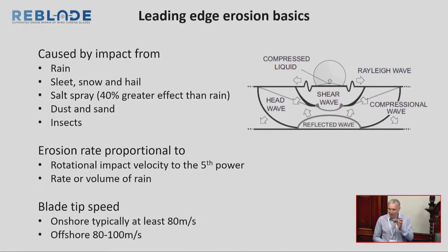Okay, so it makes a massive difference as that tip speed comes up, and people are only just starting to realize that, which is why a lot of offshore turbines that were designed for 25-year life are finding that their leading edge erosion problems are starting after about 2 years. This is a big, big, big issue. Also offshore, you tend to get more rain. So that relationship is about 2/3. So that's also having an issue as well.